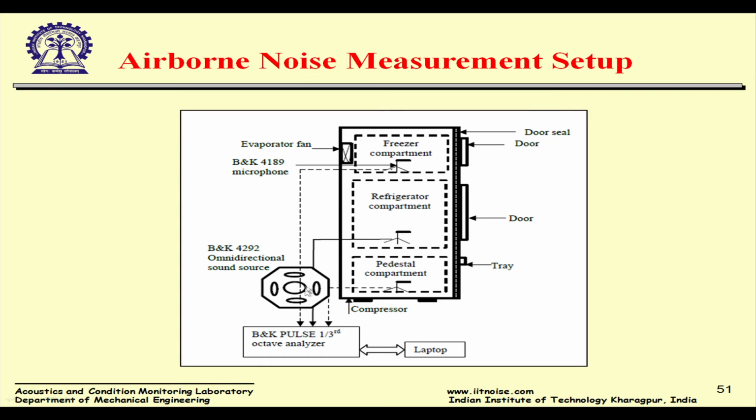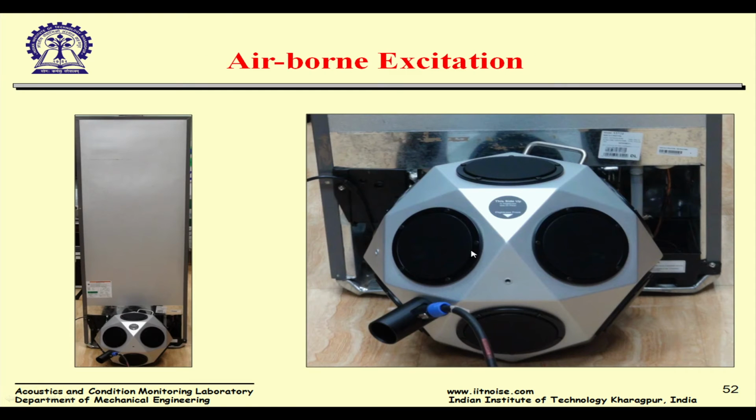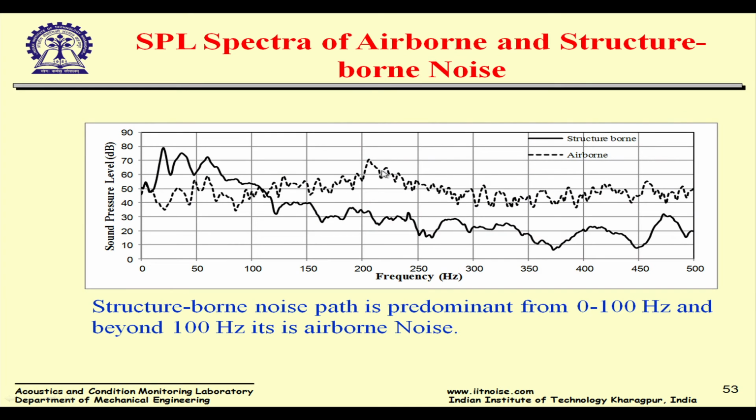This is the omni source, a sound source, and these door seals are very important. The omni source is driving the airborne excitation, and then you can see the paths for the structure borne and the airborne. As you see, the structure borne in this case happens to be predominant again at low frequencies, and airborne is high at higher frequencies. This is typical for some of these machines of that nature. So structure borne is predominant from 0 to 100 hertz. So it is these mounts which are the naughty guys in this case of the refrigerator.